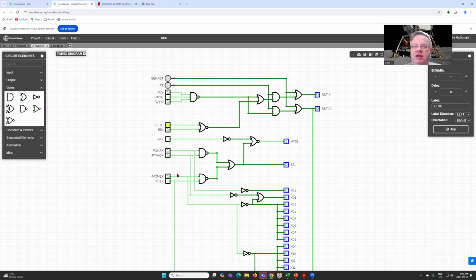And now we have our write logic for loading data in. So if we have our A2X, we're going to assert that. That is our write control for when we enable the registers to load data. And again, it's negative enable, so this goes to 0, versus the reset, which is actually reset on positive pulse. So if we go to 0, we've asserted the A2X signal. We're going to assert our write, and we'll have our selection value at 0. So that means it will pick out the A register inputs for the X register.